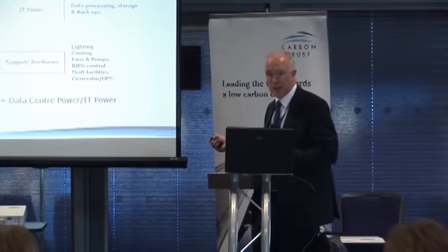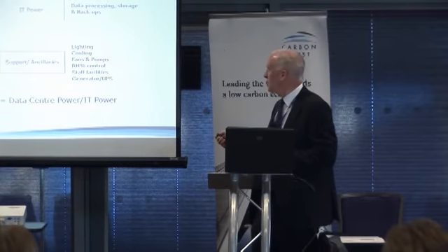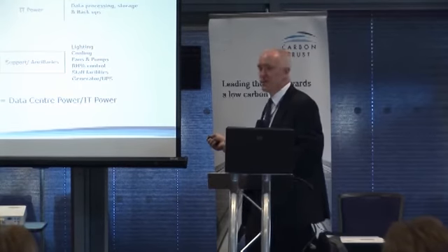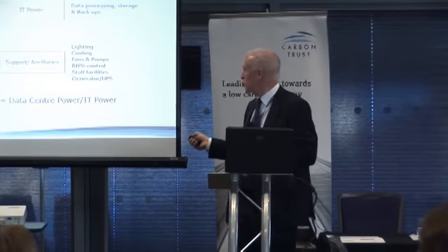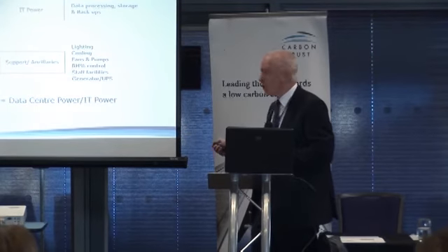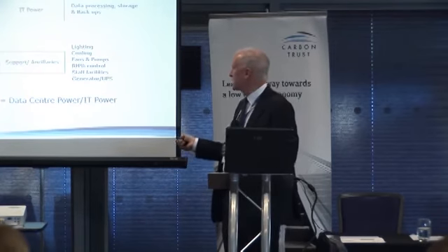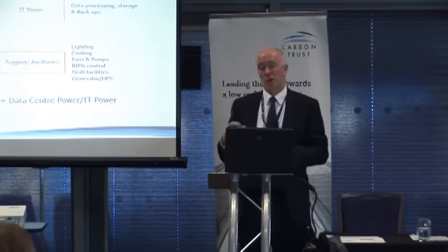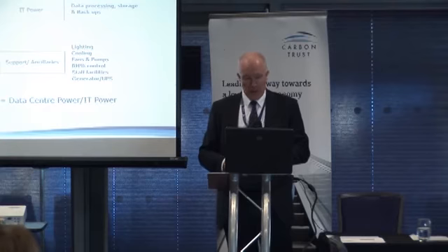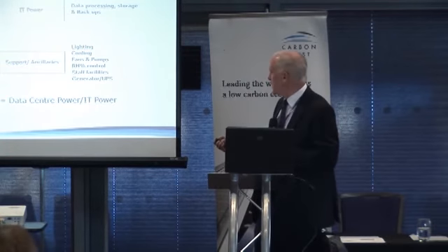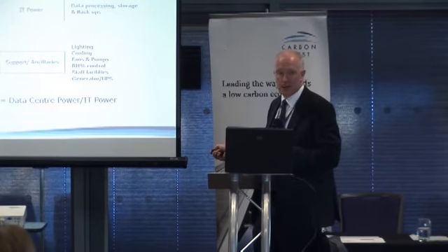That might be your UPS battery storage, the lighting, the cooling on the roof, the fans to move the air about, pumps to move the water about, humidity control systems, any staff facilities associated with the data center, all of those things. And so you've got the total power. And the power usage effectiveness, PUE, is the total power in divided by the IT power. And so we're trying to get a ratio there.